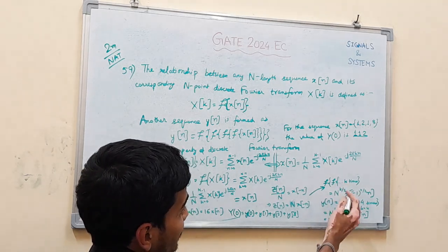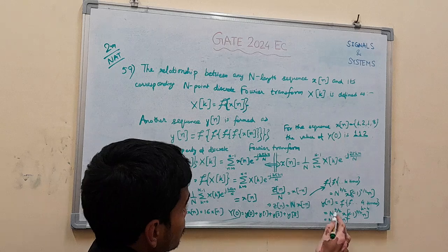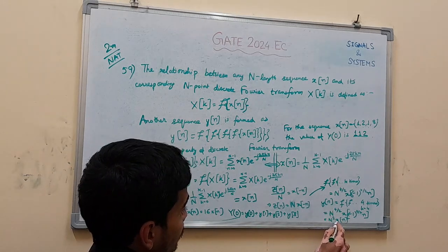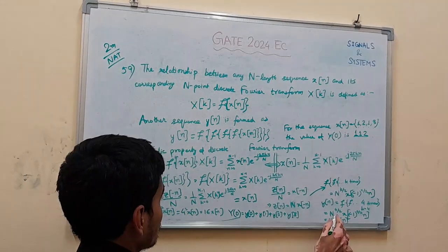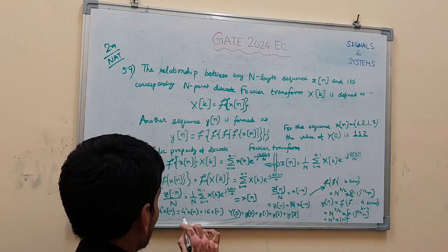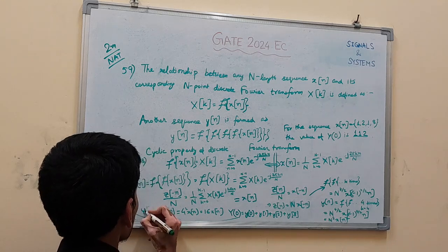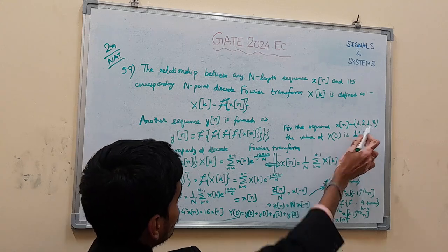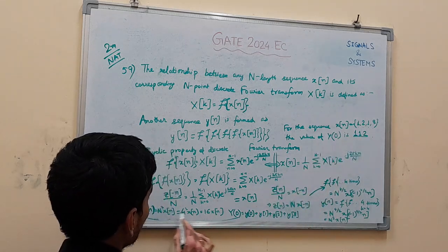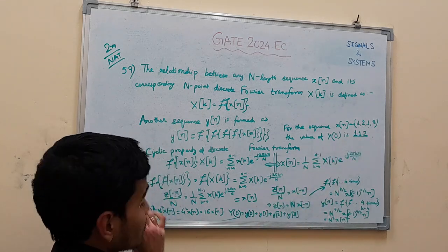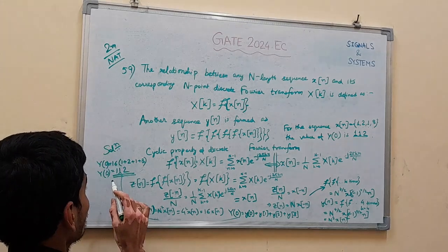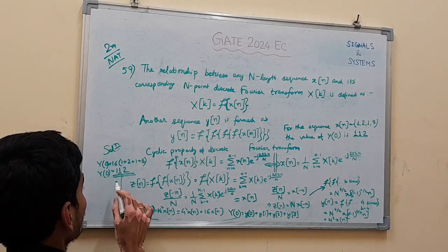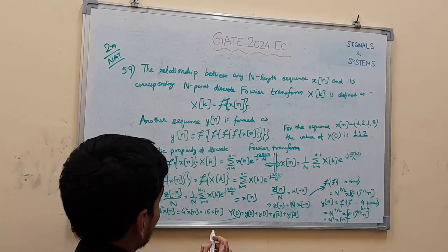So here k is given as 4, so 4 times Fourier transform is taken, so we get y of n as n square x of n from these relations. So we put n equal to 4, the length of sequence is 4, 4 terms are there, so we get y of n equals 16 x of n. Now capital Y of 0 is the Fourier transform of y of n calculated at k equal to 0, zero frequency.